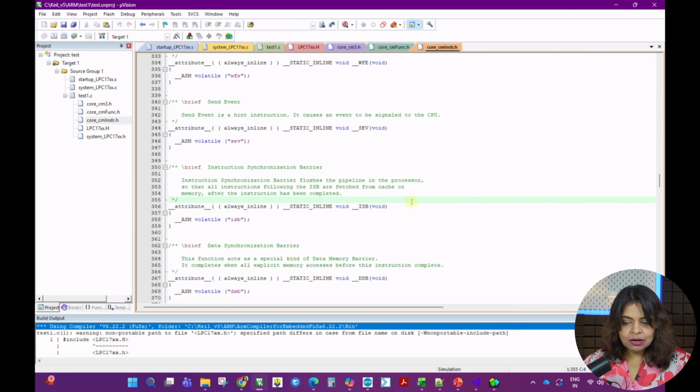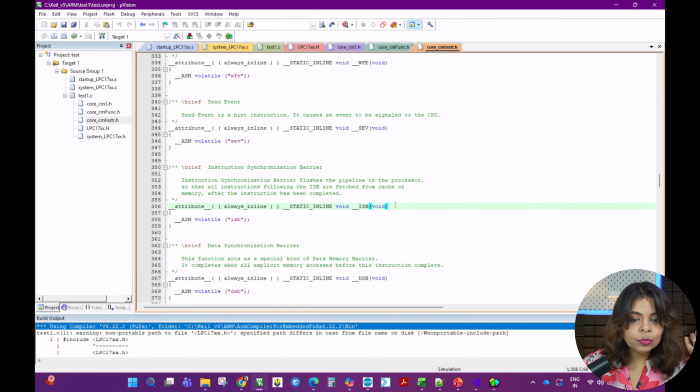So now that we have covered creating a project and adding C files, mandatory files like startup code, system initialization, I'll take one sample project and explain how we can develop the program and how we can test it in the simulator. Because I did mention it in the previous video, here I'll be discussing how you can write an assembly program in MDK, because it's a very crucial requirement. In an assembly program, as I already highlighted in the previous video, you have good control on the processor. You can make the processor execute the way you want. You can have a control grip on the processor. So for that, you have to write an assembly program.